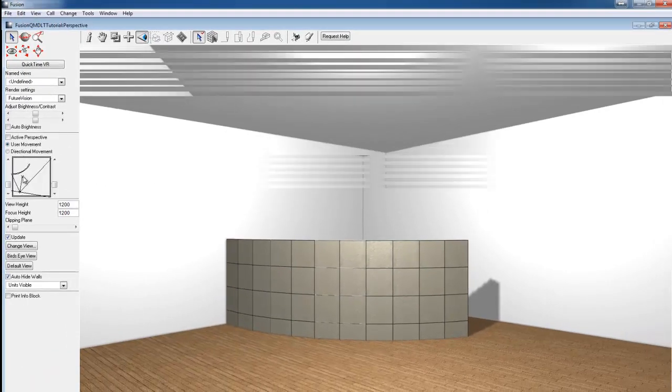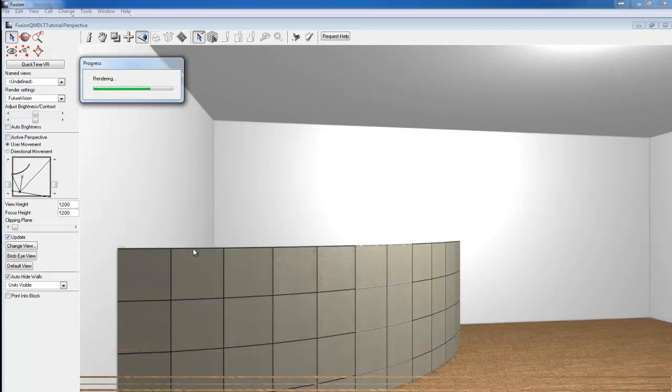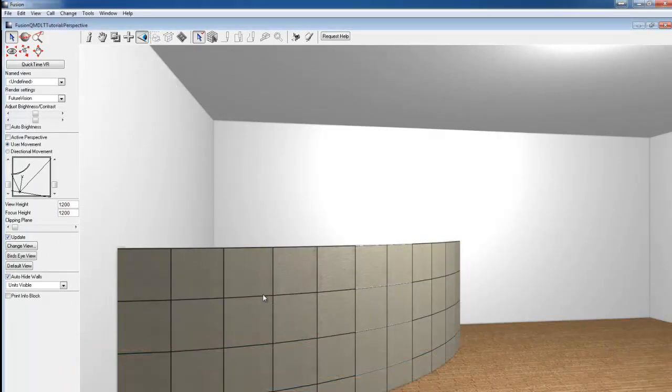Now this principle of creating the curved surface could be used for multiple things. Maybe you're creating a curved bar. You can just use a star box, 60mm thick, and set it to 100mm wide, and you do use the same principle and you can get very nice curved surfaces. Obviously the smaller the length of the box originally, the smoother the surface of the curve will look.